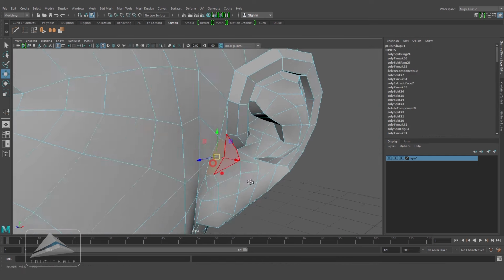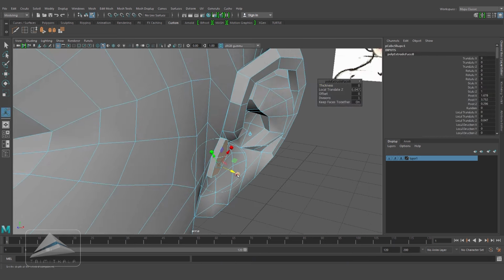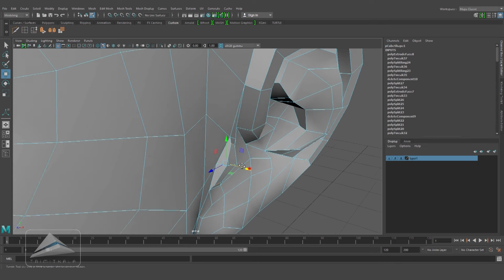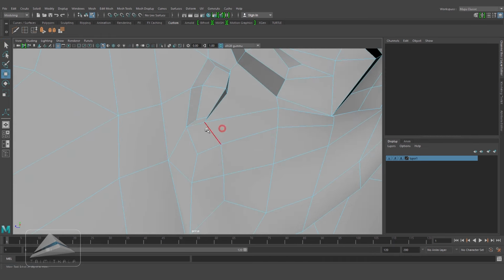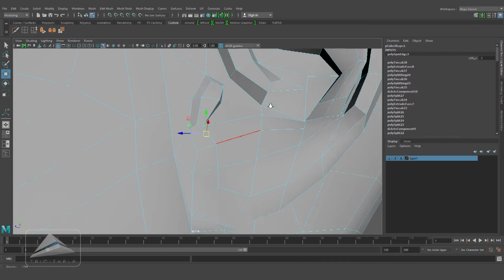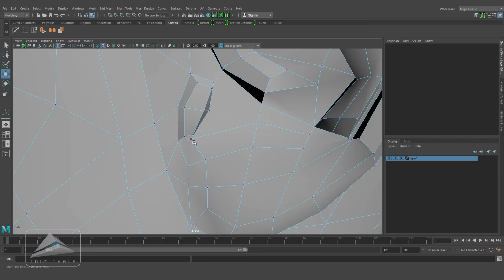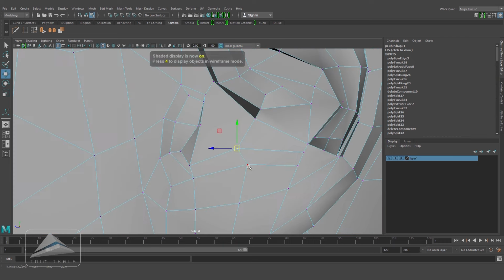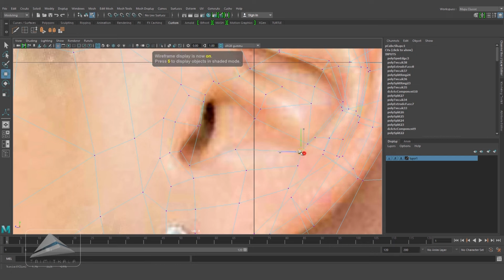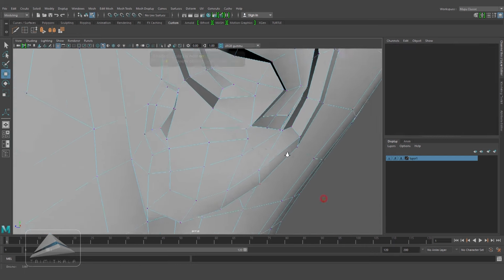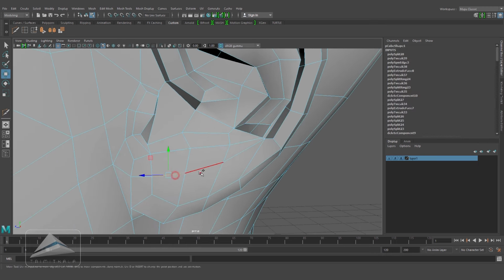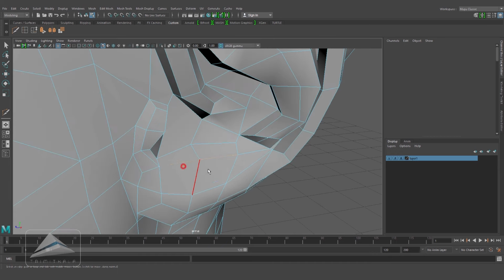Now I can select the faces and extrude it, pulling it out and scaling it down, and by selecting the edges I will push it inside so that the area will look a little bit circular. Now selecting this edge and spinning it and trying to create a continuous loop. Now by selecting the vertex I am modifying it according to the shape. In this area, this face is having 7 vertices, so I will split it and will try to create the quad. Still I can see 1 pentagon. I will modify that also.